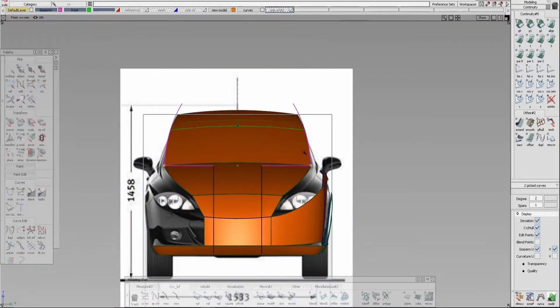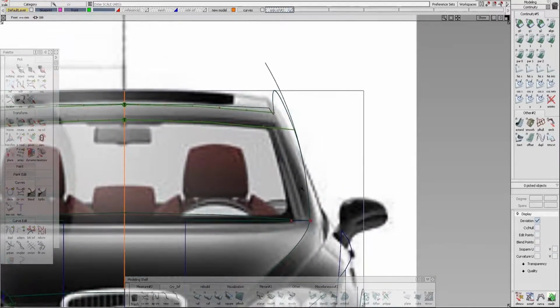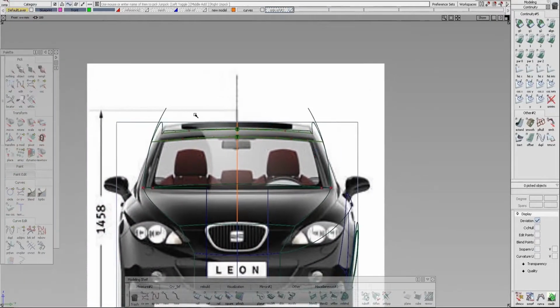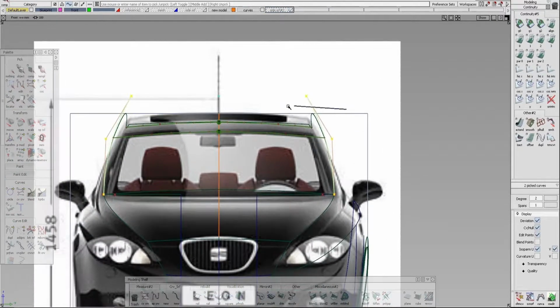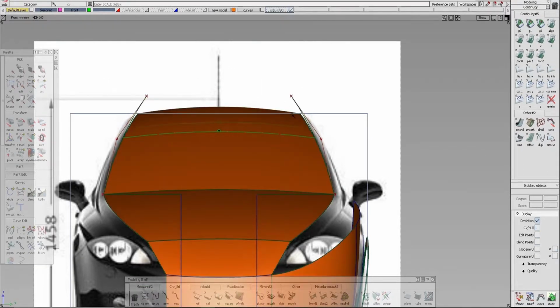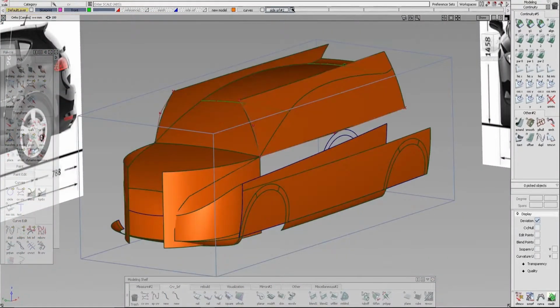But I don't like what it looks like in F9, so I'm going to also edit this curve. So if I put the points on, I can select the opposite CVs and then center pivot and scale them closer until we achieve something that we like. And then again select CVs, center pivot, scale down like that, and then we get closer to the blueprint. So I'm just doing the final touches. Yeah, that's not too bad, it's looking nice. So I'll go with that.